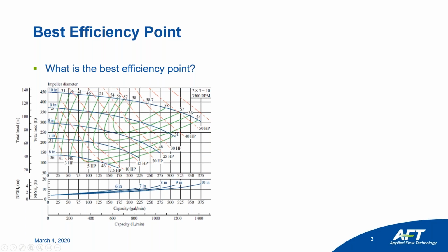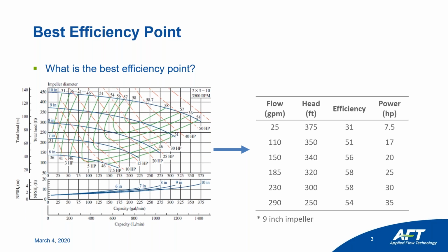In Fathom, you can't really import an image like this, but it's really easy to digitize these plots, get points for not only your performance curve, which is going to drive all of your flow in your model, but also account for either efficiency or your power. So we can turn this plot, which has a lot more information than we need, into a nice table that's easy for Fathom to interpret. And this was done with just a web plot digitizer. You can also do it by